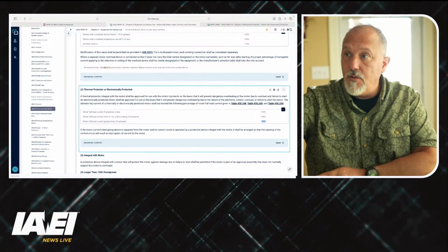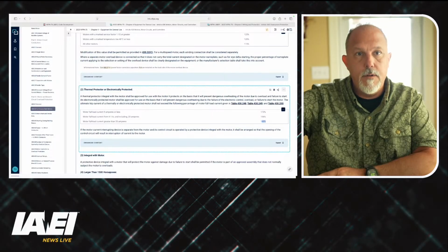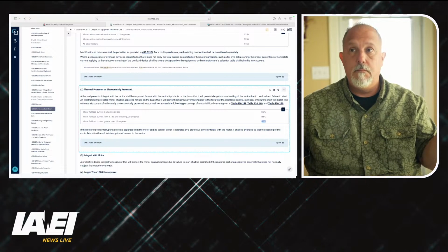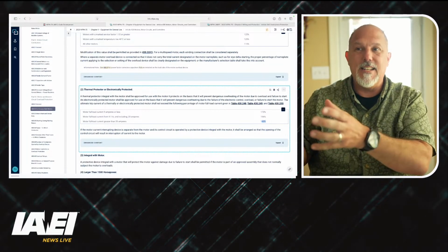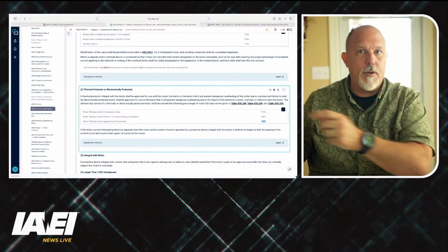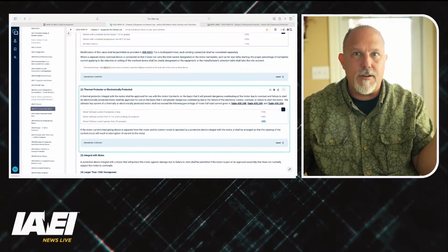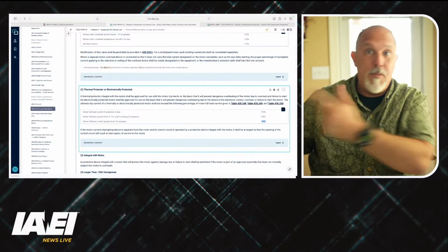Because I'm giving you special provisions for these motors to go to a larger value of overcurrent protective device because I have thermal capabilities and for protection of the motor. I don't have that same thermal input coming from the conductor. So I can't tell you if my conductor is overheating. I can tell you if the motor is overheating.